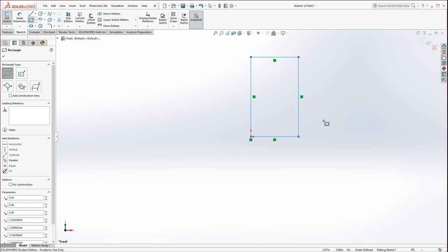And these relationships are common elements of geometry, such as parallelism, concentricity, perpendicularity, horizontal, vertical, symmetric. So all these different options enable you to draw very exacting. The days of using older CAD systems that didn't have this are pretty much gone or going away. This eliminates what I would call the challenges that one would have to actually draw extra lines and trim them up. SolidWorks has eliminated a lot of that. That's from the very start when they introduced the software.